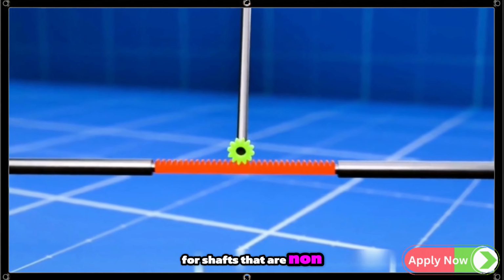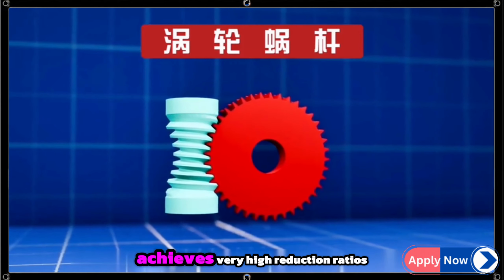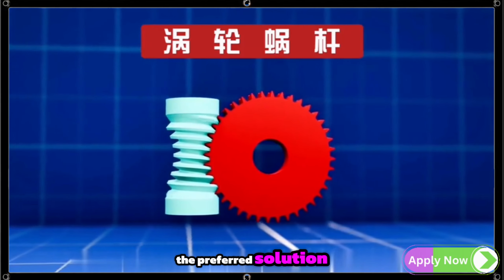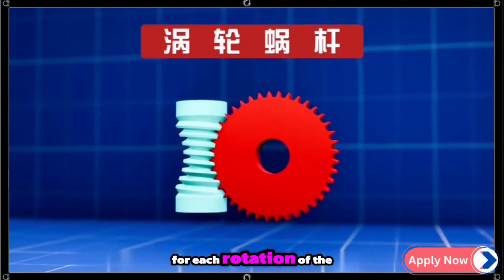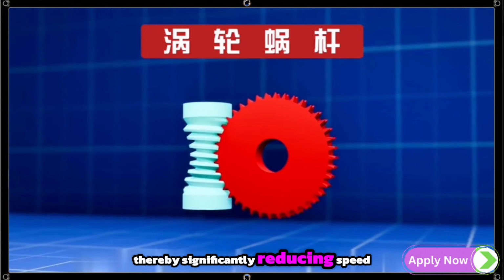For shafts that are non-parallel and non-intersecting, typically between shafts at a 90-degree angle, where you need very high reduction ratios, worm and wheel are often the preferred solution. A worm and wheel set consists of a worm that resembles a screw, and a wheel that meshes with the worm. For each rotation of the worm, the wheel advances only one tooth, thereby significantly reducing speed.